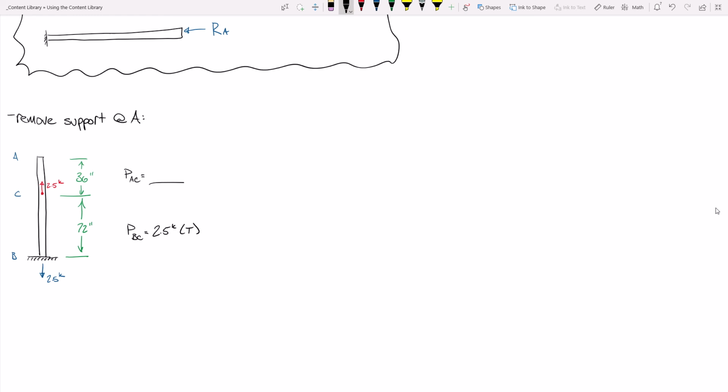All right, here's what I want you to do. How many of you have a pencil? I want you to grab one end and then grab the middle of it and yank it. How much force is this free end experiencing? You need a higher E value for your pencil. Now, hold on, watch my hand. I'm yanking. How much tensile force is in this part of the pencil? None. This is 0. Does that make sense?